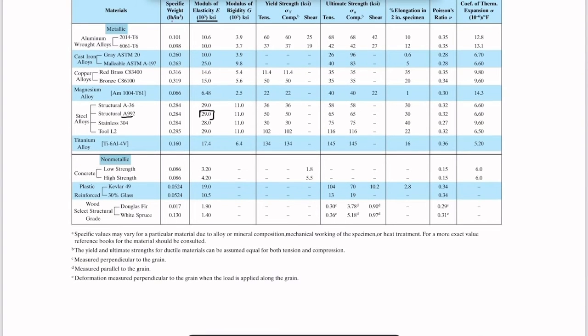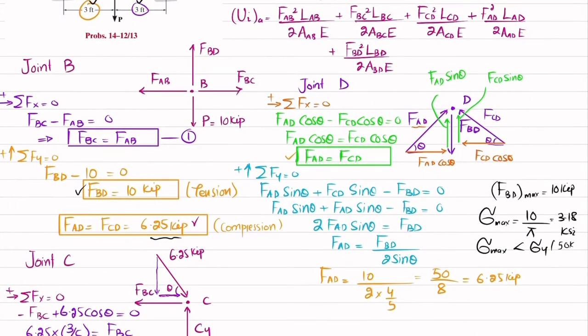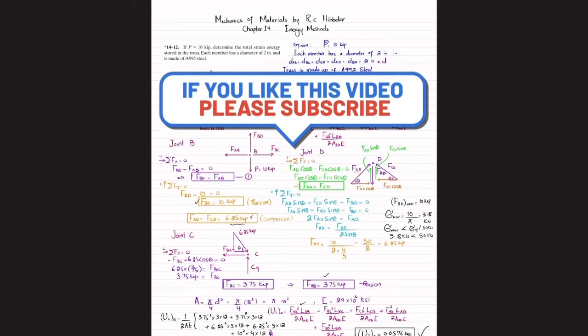I don't know why my pen is not working, but you can see in the row, this is 50 ksi. So I will write 50 ksi. You can see 3.18 ksi is less than 50 ksi. So it means that it will not fail. Clear? And the amount of energy stored by the truss is 0.0576 kip-inch. And that was all about this problem 14-12.